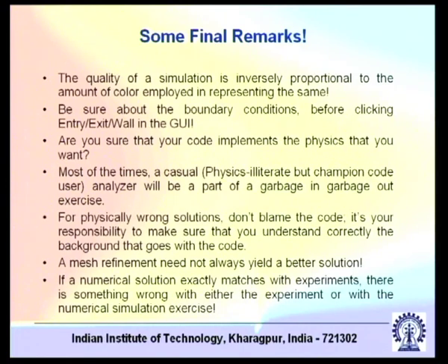If you are solving for θ as a variable and then implementing the outflow boundary condition, fine, but not if T is the variable. So you have to be very, very careful whether the boundary condition you are implementing is representing the right physics.